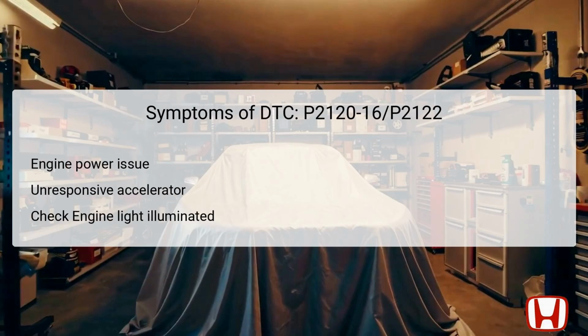When DTC P2120-16 and P2122 is active, drivers might experience various symptoms. One primary symptom includes a lack of engine power, where the vehicle does not respond effectively to pedal input. This unresponsiveness can be dangerous, as it may significantly hinder acceleration.